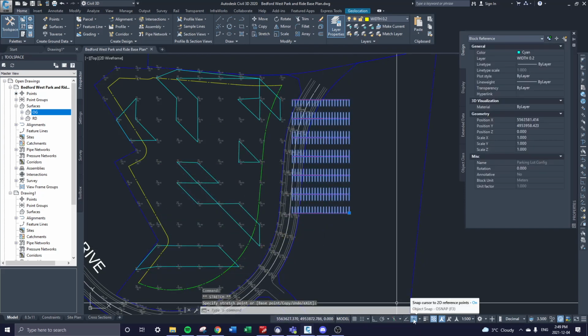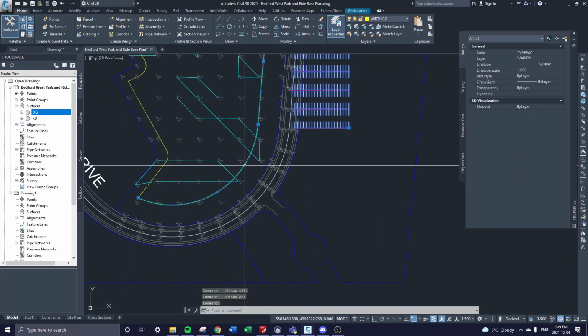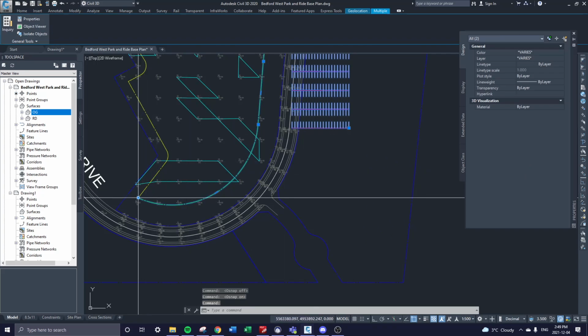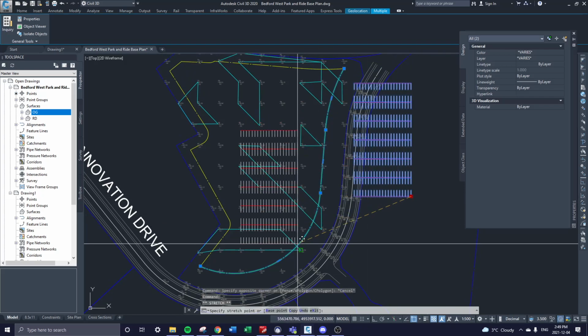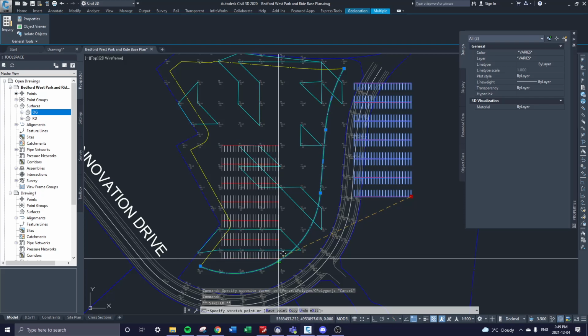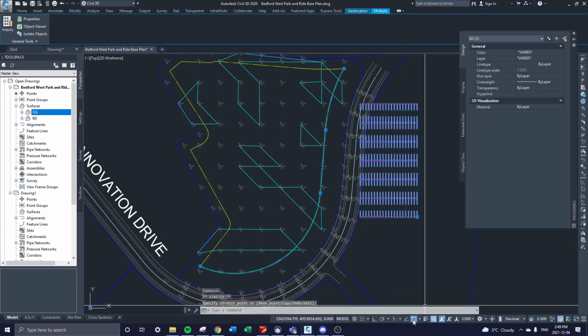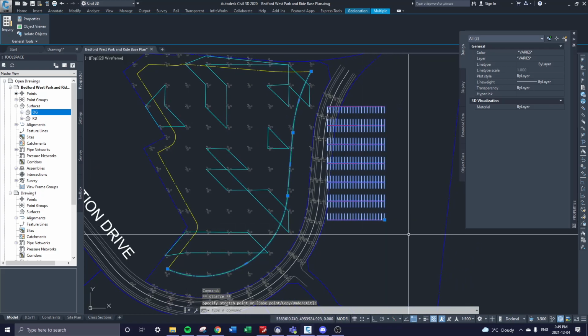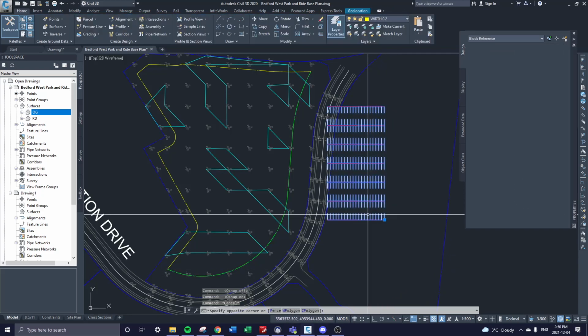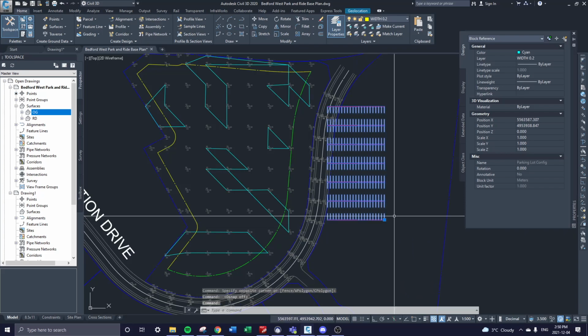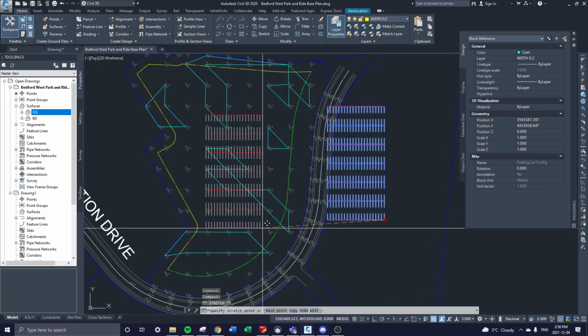Again, you might benefit by turning off snaps. If you don't know what snaps is, it will automatically try to pick these grips. And that can be kind of annoying. If you want to put it here, you see how it will try to put it maybe not as precisely. So you can just turn that off. A shortcut to turn that off is F3. You see what I'm doing when I type F3, that thing's turning on, off, off. Come on, okay. I guess I did it too many times. All right, so that's just another shortcut that you can use.